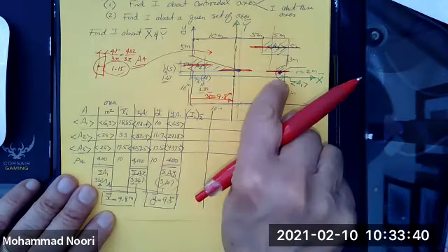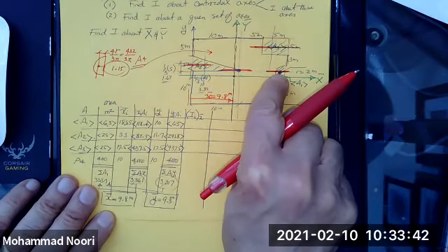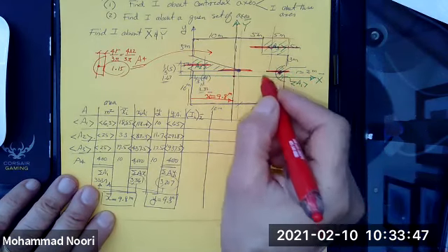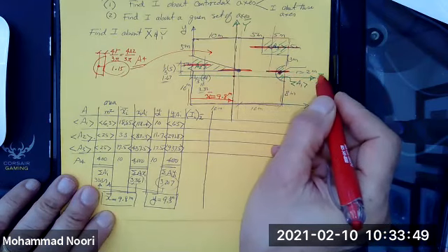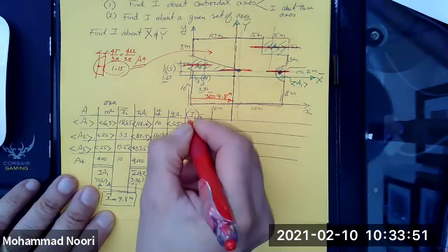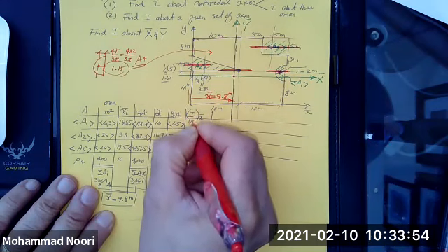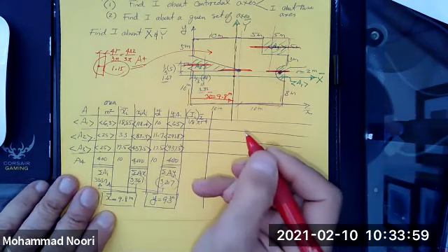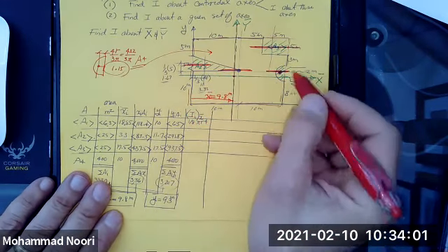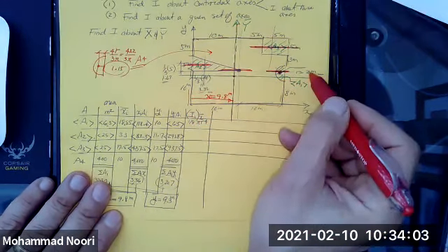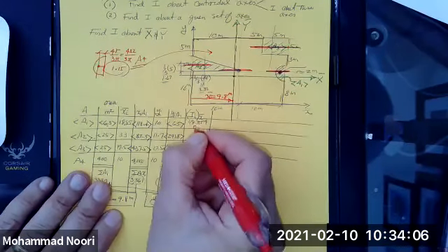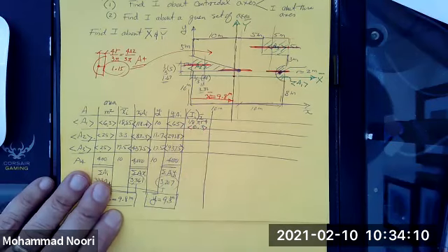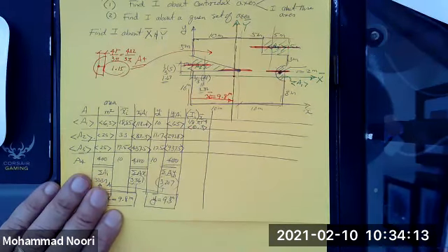So you go to that table. For this half circle, the moment of inertia about this axis is tabulated as 1/8 of pi r to the 4. So 1/8 pi times 2 to the 4 gives you 6.3. This is a negative area, so that's a negative value.